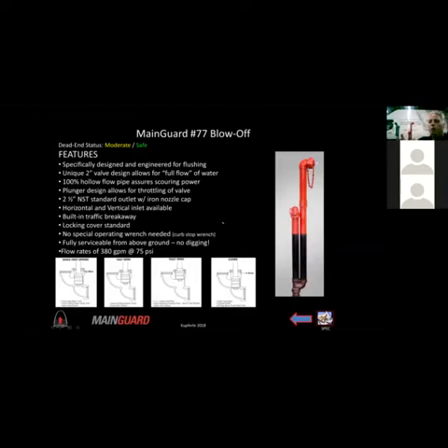when you pull the plunger up, when you open it up, like a fire hydrant, the water goes around the plunger, just like a fire hydrant. So it comes up and the water goes around the plunger. This one has a little different design in that it has a 2-pipe design where the plunger is down here. As you can see here, it's in the closed position. And I can actually throttle this one from about 1/4 of the way open to all the way open. So I don't have to open this one all the way before the weep hole is closed.